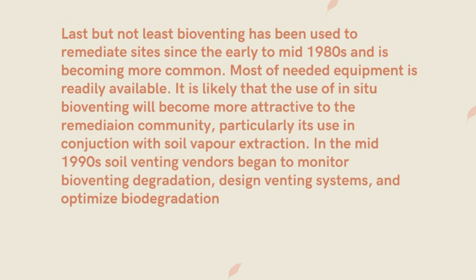Last but not least, bioventing has been used to remediate sites since the early to mid-1980s and is becoming more common. Most of the needed equipment is readily available. It is likely that the use of in-situ bioventing will become more attractive to the remediation community, particularly its use in conjunction with soil vapor extraction.